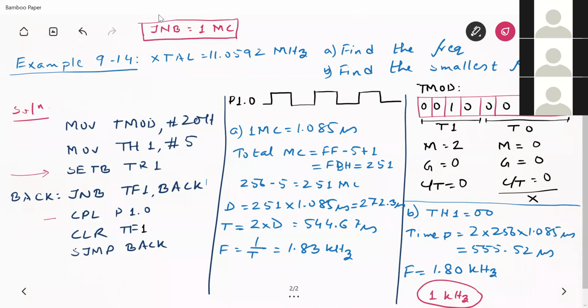And we'll place this line after the delay. So instead of calling the delay one time, we will call the delay multiple times, say 2 or 3 times based on our requirement. So this delay will increase, right? Because you are calling the delay 2 or 3 times instead of just once. So if your delay increases, your time period will also increase, isn't it?